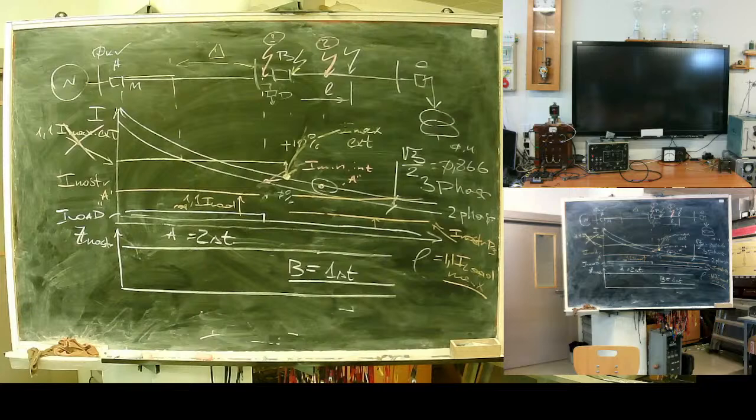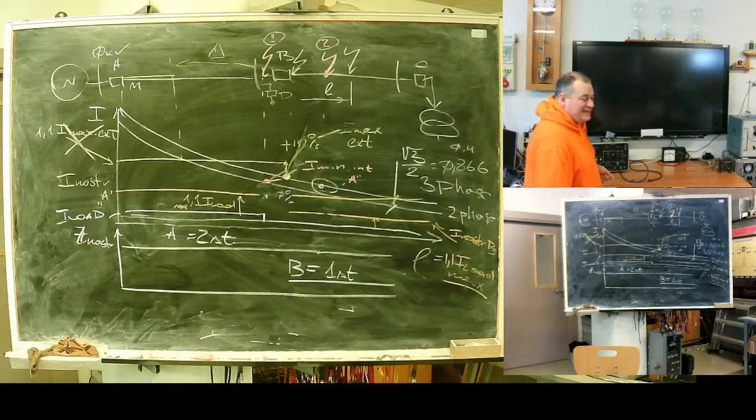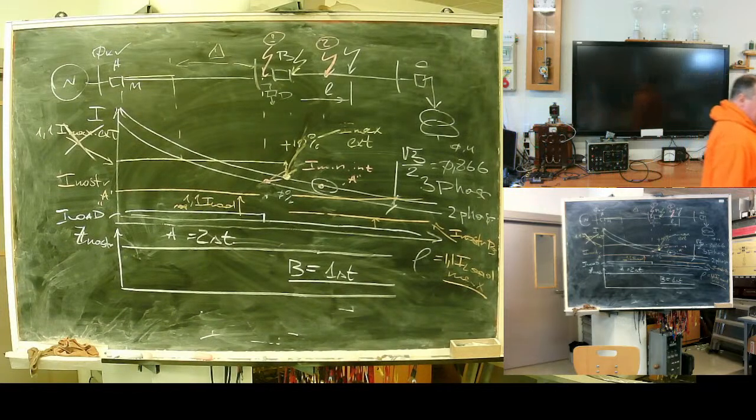In such a schematic, selectivity is achieved by time delay. They both start, but because B has a smaller time delay, it operates first and disconnects the faulted line.